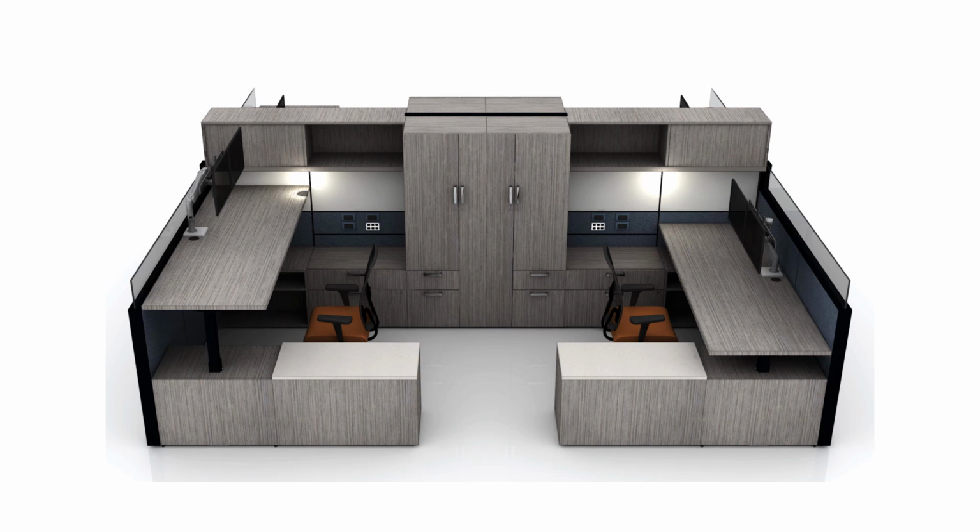The reason behind this being, there is not a single cantilever in this layout. So how on earth is this staying up? Of course, along the spine, we have the 66-inch high storage units, which are helping to stabilize the center-mounted overheads. But what about the rest? Lots and lots of storage to panel brackets. Thankfully, the manufacturer already had those, and thankfully the storage unit seen here already had reveals to house these special brackets.